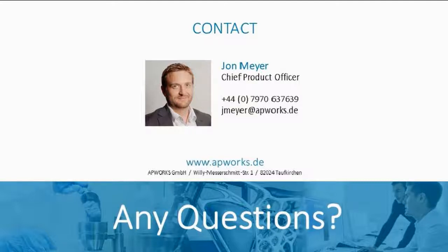Okay, so inclusions is an interesting one, because I guess it's an obvious question to ask when you deal with powders, where you have a high potential for something to get mixed in there. In general, the control of that is through very tight quality control, but it can happen even from the powder manufacturers that you could have an inclusion. Generally, when an inclusion might be critical, we're looking with X-ray or tomographic methods at the parts.